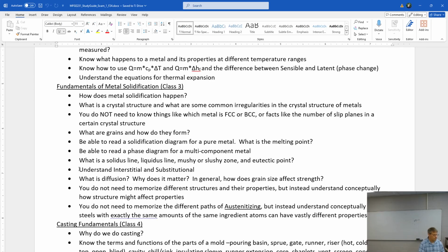What's the carbon scale that comes out of quenching? Does that come out of the material where it was drawn out? Or is it... The carbon scale, I think, comes from the material on the outside just because it was hot worked, and so it is reacting with everything that it can. It's reacting with the air, the oxygen in the water, and the oil, whatever it's doing, it's reacting with all of those. So I think that's where it comes from.